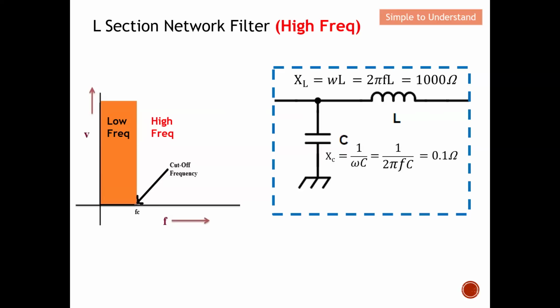So with this, I think you have a better understanding in terms of the design using lumped elements. Let's kickstart the discussion here. If you still remember, this is what is required to point: whether the L is supposed to be on the right or on the left. For this case here, it looks like a gun. Imagine that the gun always points to the smaller impedance.